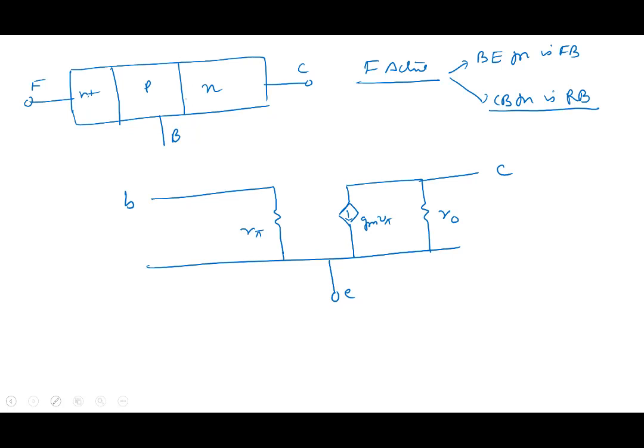In a reverse bias diode, right? Did we say that as the frequency goes up, the reverse bias diode has a capacitance? Diode has capacitances in it. Reverse bias diode has which capacitance? Depletion capacitance only. Remember, if I have a diode here, a PN junction, there's a depletion region that we discussed. And in reverse bias, there's nothing but a diode capacitance which we call CJ, right? And we say CJ equal to CJ0 and all that expression.